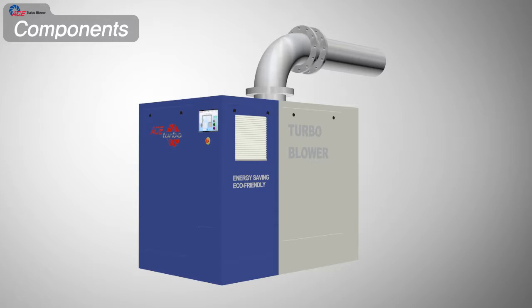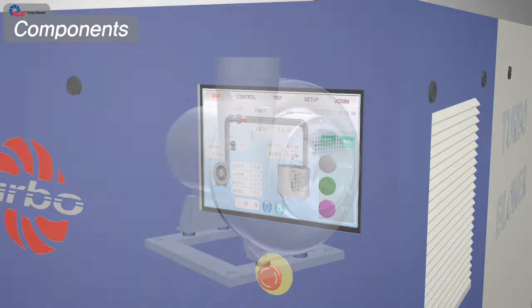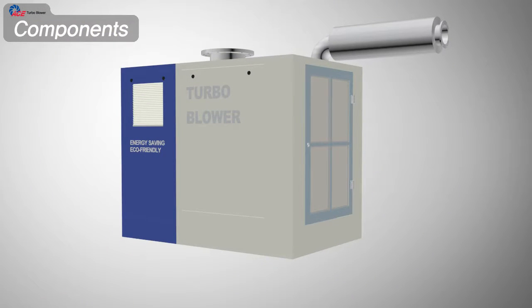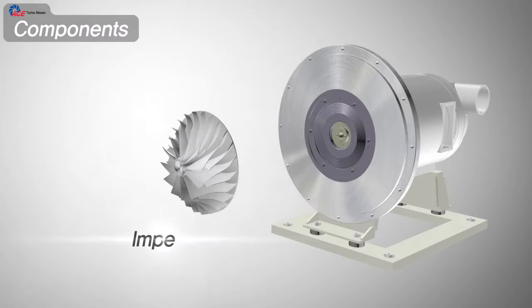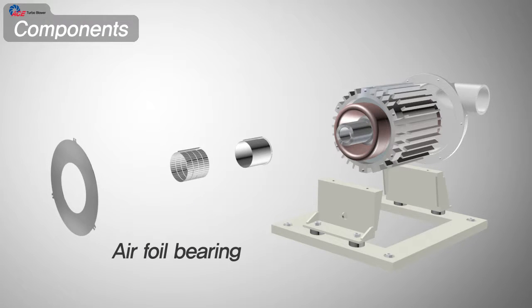The turbo blower mainly consists of 3 parts. First one is the control part, the electric panel and inverter for controlling the blower. Second one is the air end part for compressing the working fluid, especially the air. Finally, the cabinet for inducing air and the sound insulation. The core component of turbo blower is the air end part, which consists of the impeller, thrust airfoil bearing and journal airfoil bearing.